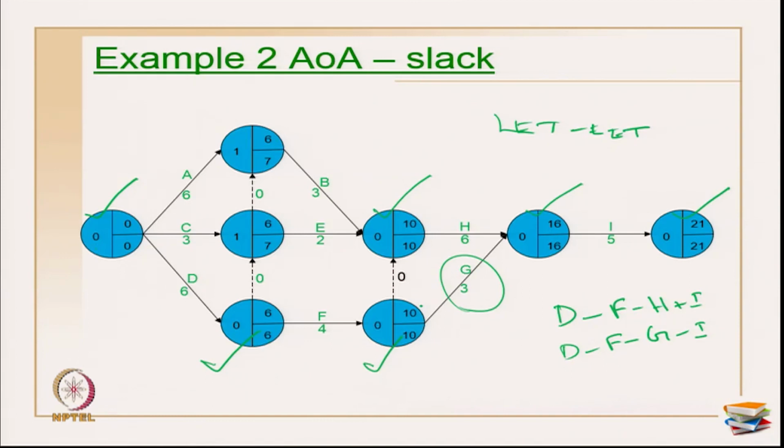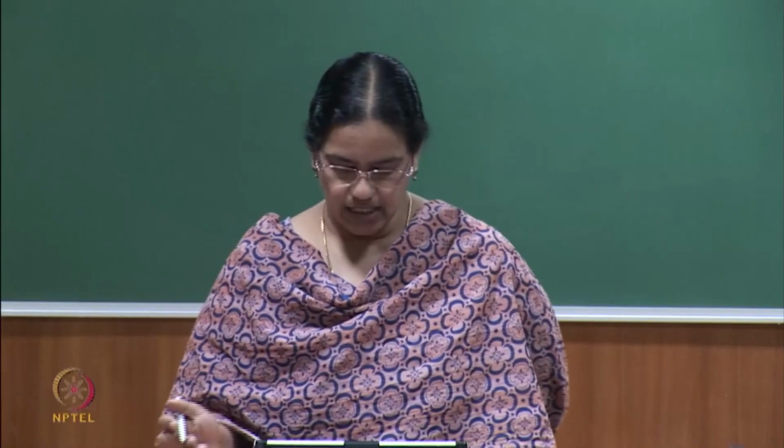The other disadvantage is sometimes you may be misguided by the values in the slack calculations. Okay. What to do in these cases? You may have to again work out all these activities and cross check your values, whether they are on the critical path or not, and then you have to go ahead with the calculations. This is another big disadvantage in an AOA network. Okay. That is where people started preferring the AON method.